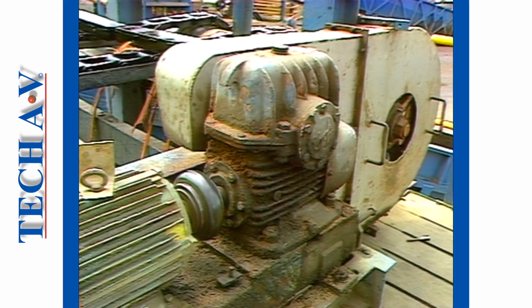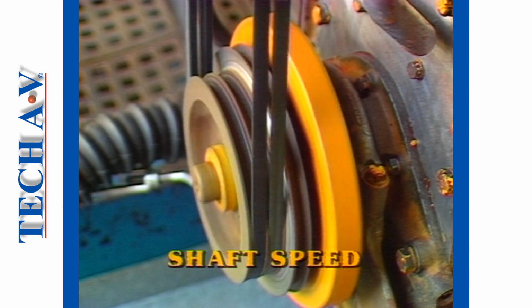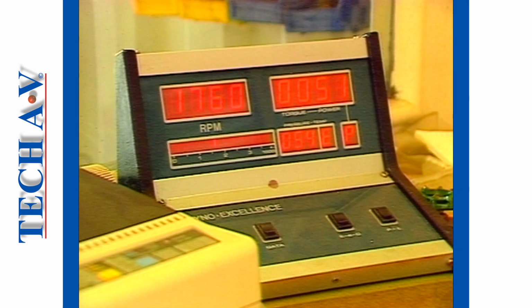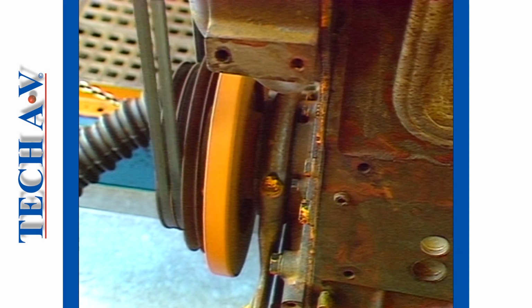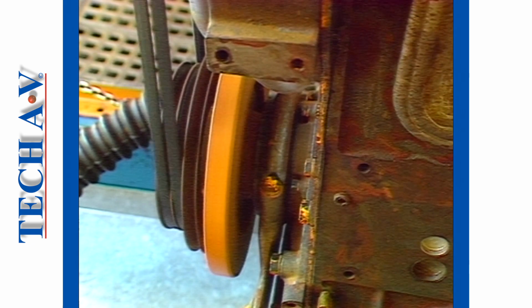The next consideration is shaft speed. Nearly all standard rotary shaft oil seals are limited to shaft speeds of a maximum of 18 meters per second. However, on shafts below 35 millimeters, the revs per minute are more critical and they should not exceed 7,000.